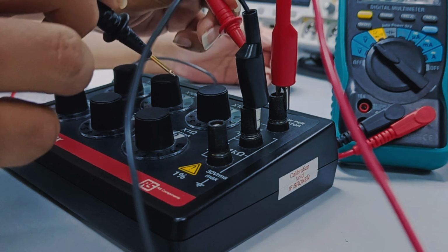Now the capacitor circuit. We have assembled the circuit in series and it is also connected to a DC power supply, which is 5 volts. First, we start off with measuring each component's value. In this case, we measure the capacitor only because my friend has done the measurement of the voltage and resistance. We connect the components using jumper wire. Turn on the power supply.